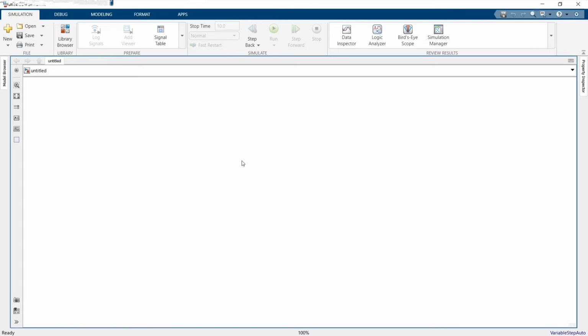I'll edit the value of my inductor. I'll provide a value of 0.005 Henry and a capacitance of 1000 microfarad. So my EMI filter is done. I'll name this one also ground. Why? Because this subsystem needs a ground. An EMI filter needs a ground.